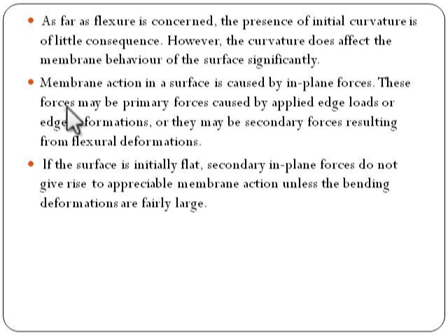Then, as far as flexure is concerned, the presence of initial curvature is of little consequence. However, the curvature does affect the membrane behavior of the surface significantly. Membrane action in a surface is caused by in-plane forces. These forces may be primary forces caused by applying edge loads and edge deformations, or they may be secondary forces resulting from the flexural deformations. And if the surface is initially flat, secondary in-plane forces do not give rise to appreciable membrane action unless the bending deformations are fairly large.